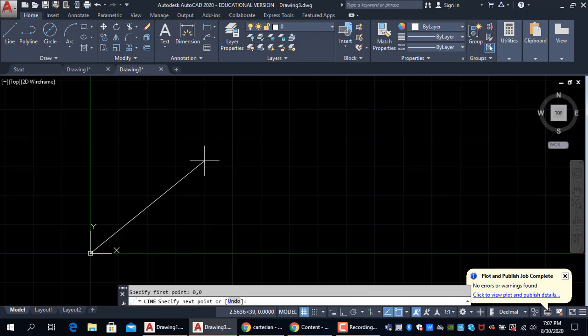Okay, so we talked about the coordinate system, the 4 quadrants, how AutoCAD sees every single point and how you can use those points as a point of entry. Every shape that we have in the drawing has specific points created and put on the actual grid. In the next video, we'll talk about the ways of inputting information using different input systems, which are absolute, relative, and polar.